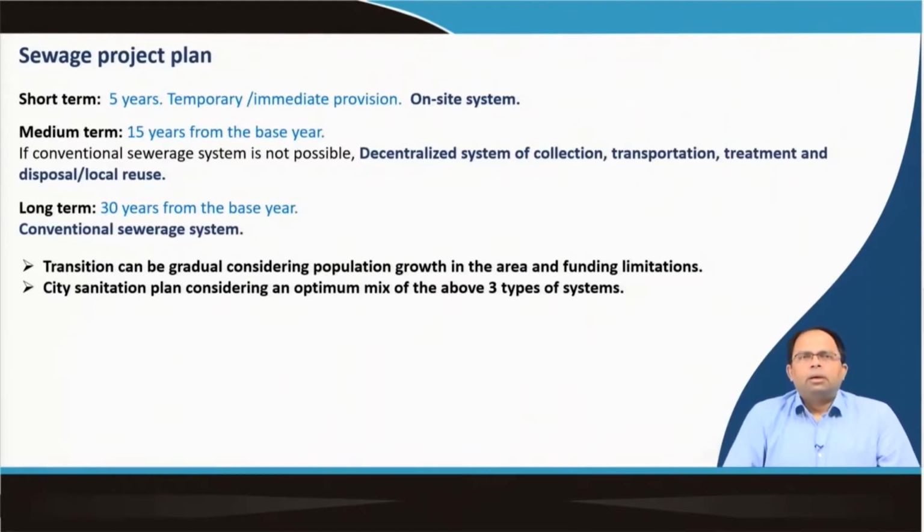So, when we talk about any kind of sewage projects or when we plan for projects, we can think in different time periods: short, medium and long. Whenever we talk about sewerage network design for a particular project, we usually think of a 30-year period as the timeline for which the infrastructure we design now will last.